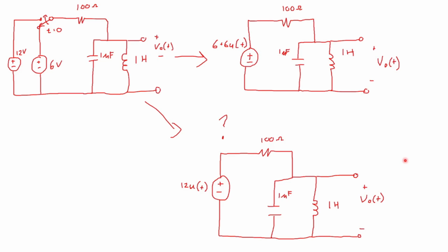If we are using the one-sided Laplace transform, both of those things are true. The Laplace transform of 1 is 1 over s, and the Laplace transform of u of t is 1 over s if we are using the single-sided Laplace transform where only the values for t greater than 0 are going to matter. And on that interval, those two functions, 1 and u of t, are indistinguishable.